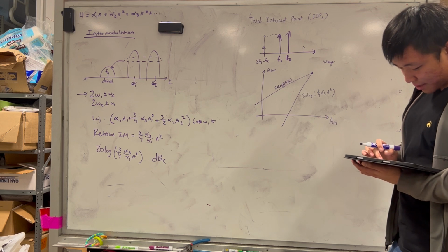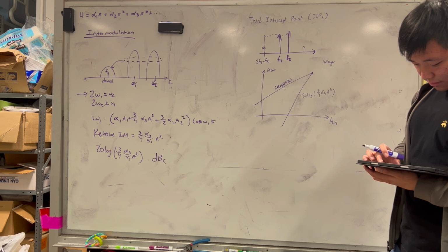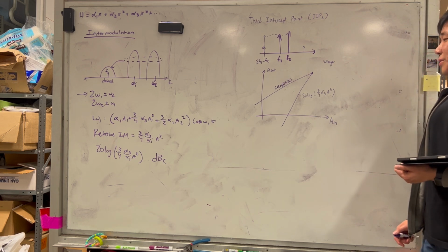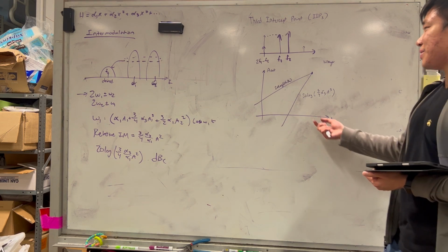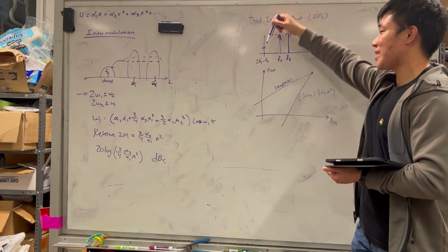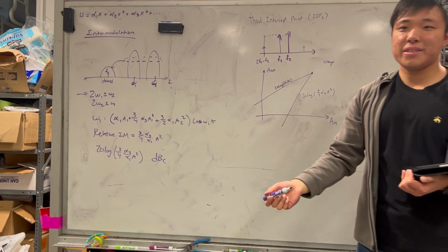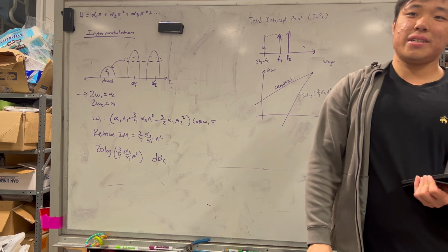You have that. And you can solve for the, actually, now, before I go into that, just for a thought experiment, I have an IIP3 point, which means at some input amplitude, you get such that the spur is going to be equal to the fundamental, right? If you guys remember, as I increase the amplitude, what other effect will happen? It'll be gain suppression.